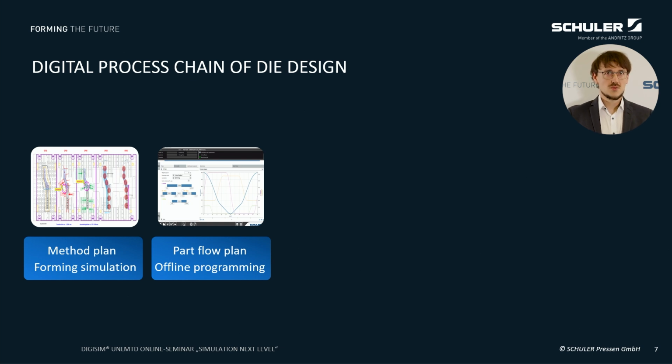With the part geometry, we are able to estimate the path and overlaps of the transfer movement and the slide path. With these assumptions, we can start the optimizer, enter these values, and receive the expected stroke rates as well as the movement curves as a result. This gives us an increased planning reliability even during the quotation and project planning phase.